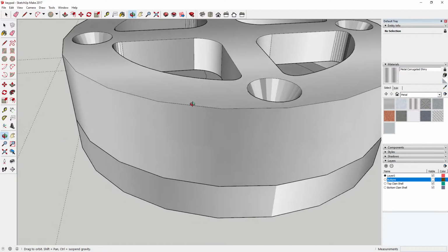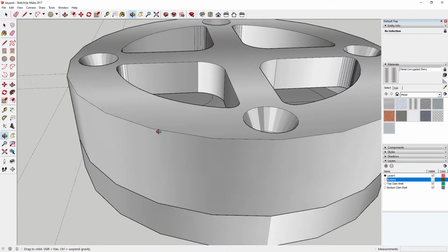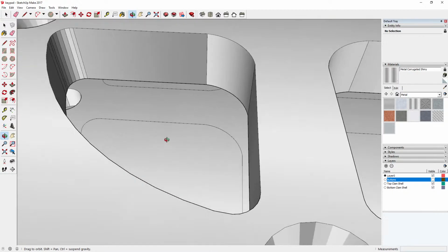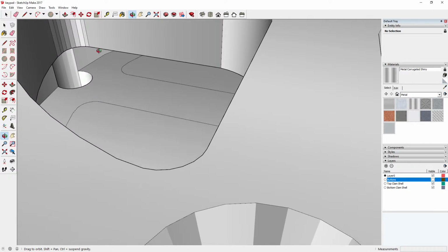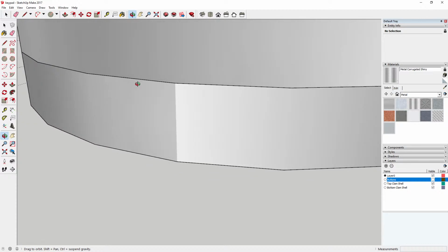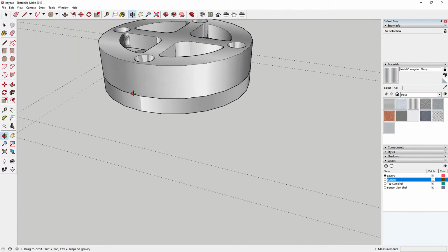Well, we're 24mm thick, minus 6, minus 6. Should have 12mm space in here. Should have. Let's measure it. So from here down to 6mm, because we've overlapped, so we've got 6mm. Right, so what have we got here? 6mm there. Don't draw a line, and we've got 12mm there. So we've got 12mm.